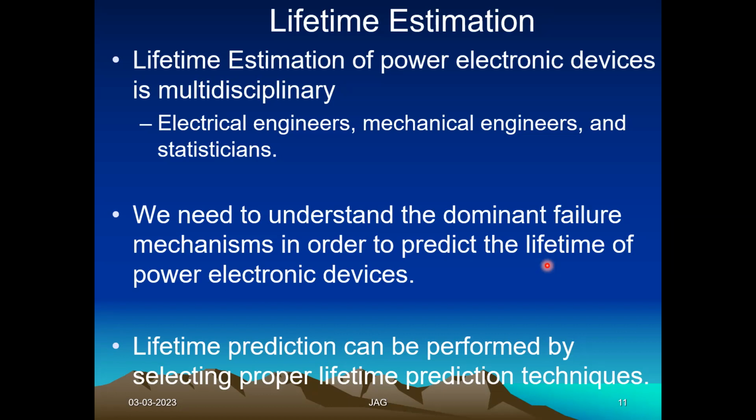Or you use a fan to cool down the heat sink. Direct a fan towards the heat sink so that the forced air will get continuously circulated and hence the temperature comes down. That is another reason why a mechanical engineer is required in this scenario. If the heat is removed, then the chance for failure will be less.